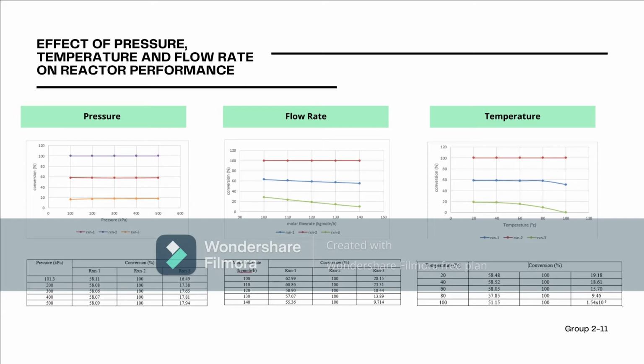From the graph, we can deduce that the conversion performance has peaked somewhere between 40 degrees Celsius and 60 degrees Celsius. This information correlates with the knowledge that treating palm oil mill effluent with thermophilic temperature generates higher gas when compared to using mesophilic temperature. Also, thermophilic temperature is 55 degrees Celsius, which is situated between 40 degrees Celsius and 60 degrees Celsius.